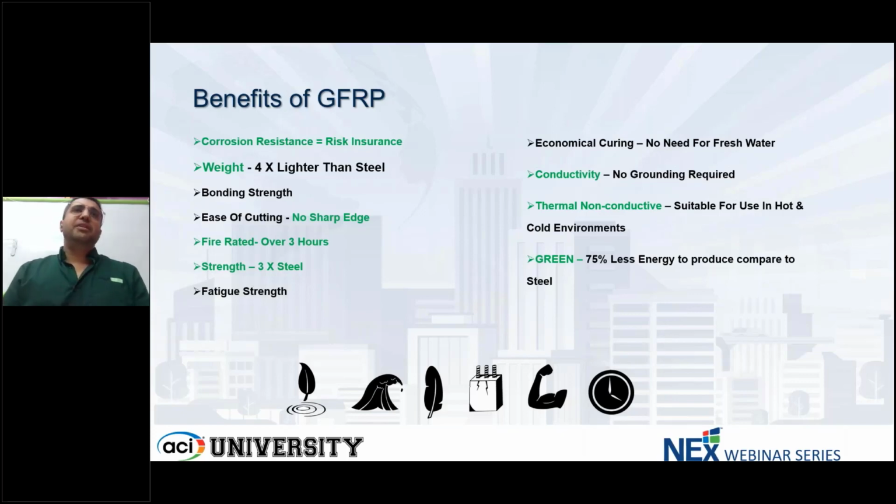The guaranteed tensile strength of some of the materials that are ASTM qualified is roughly about 145 KSI. That's a guaranteed value. In fact, in our QC, when we break these bars, we are mainly at about 200, 210, 190 KSI. So as manufacturers, we definitely want to put a factor of safety out there, so we pretty much dumb it down by 20%. And obviously, when you use ACI codes and other codes, you have more factor of safety. At the end of the day, you pretty much use the same 60 or 40 KSI that you have been using for steel. But it's all about factor of safety and public safety.